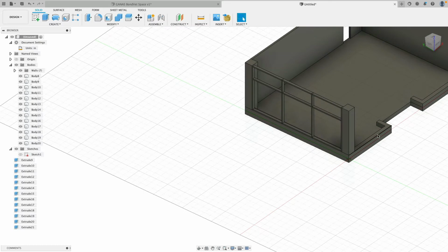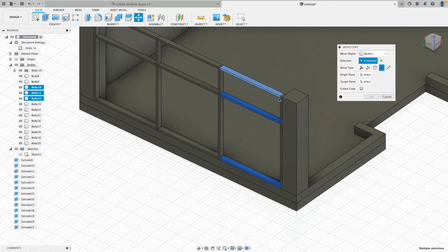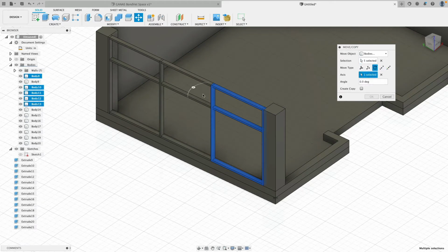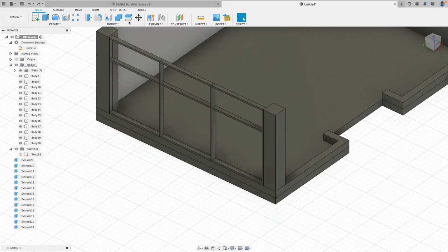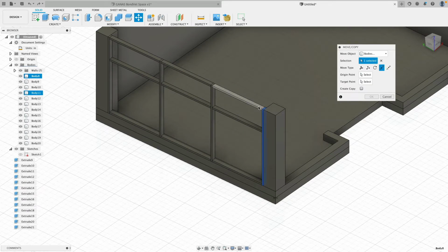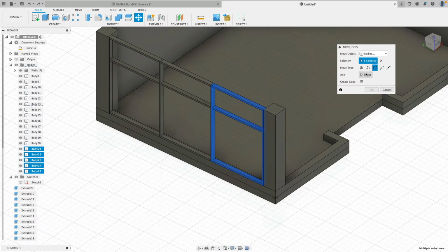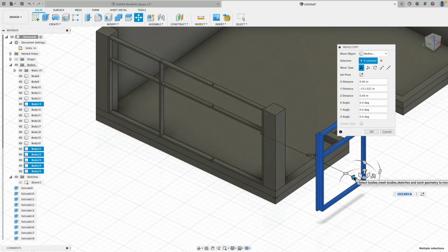Now we would like to work on the other side. Also here we have already a lot of work done, so I can select all these elements here, make a copy, rotate it. Doesn't matter what edge I select. I'm just rotating it this way. Then I go to the move command. Oh, we want to make this as a copy. Undo. So one more time. Rotate and copy there. So make sure that you really select the copy command. There we are. And then once this is done, I can switch now to move and move this to somewhere else.